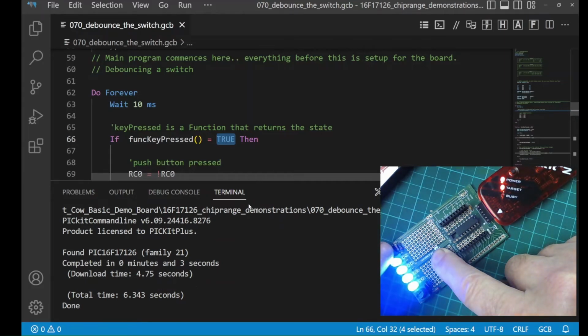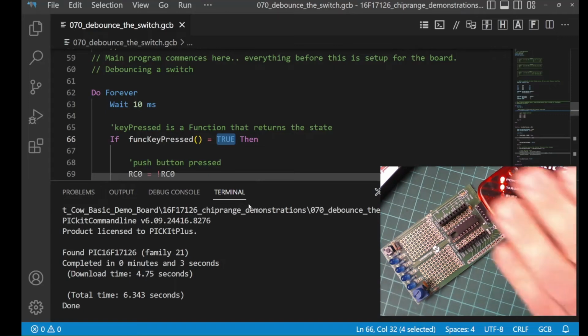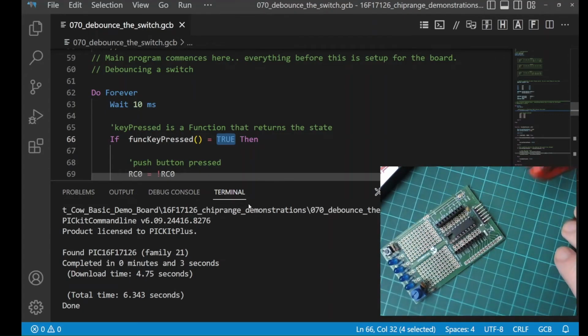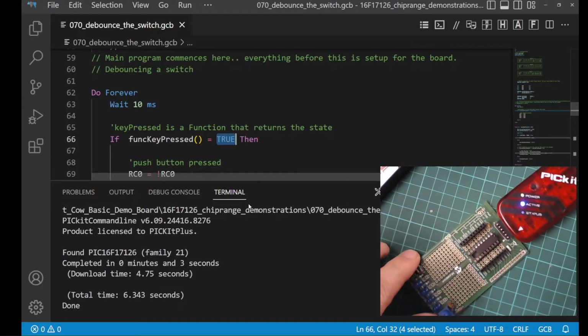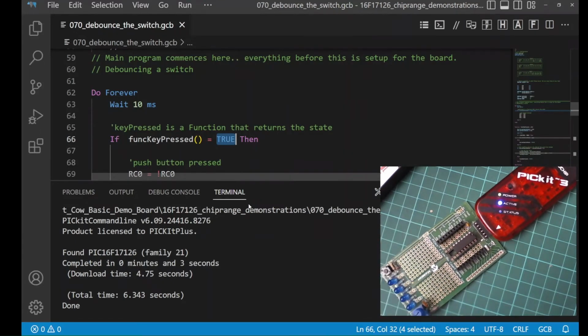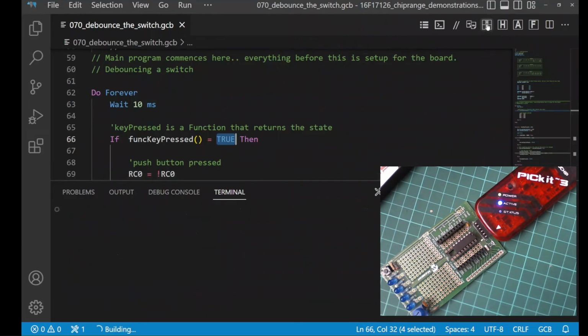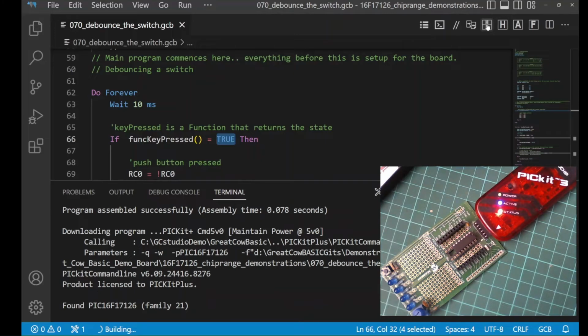So look, what I'm going to do now is just, has it programmed it yet? Push that button again. Now what I'm going to do is swap out the chip for a different PIC variant. I've changed it, make hex and flash, and it's just going to flip that over, find the new chip and just works.